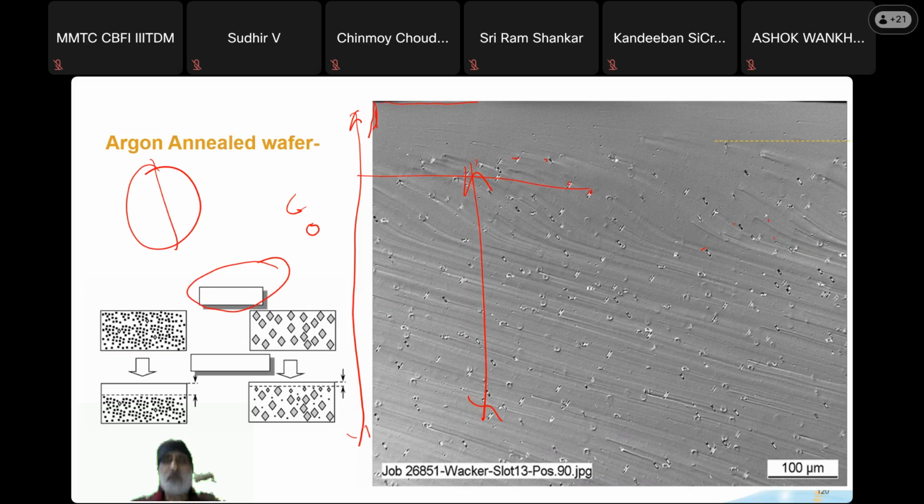The first operation: here also there will be some impurities. What we will do is annealing, and there is a step known as gettering, on the top side and bottom side. By gettering, I mean that whatever impurities are in the top 2 to 3 microns, in the top 5 micron area, I will pull these impurities down.